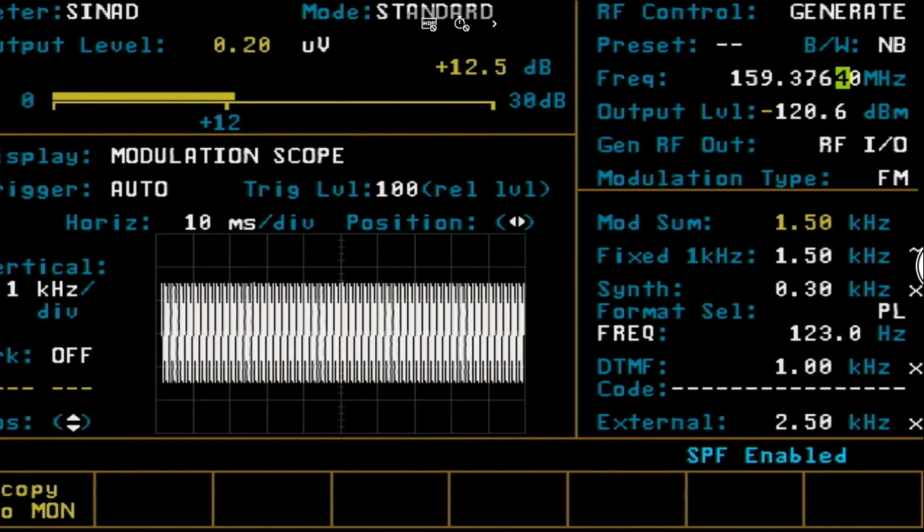So I'm going to say at 3764, my receive VCO is going to be off plus 140 hertz, which is not terrible, but there's no warping of that. That's a hardwired circuit, so there's no adjusting of that.